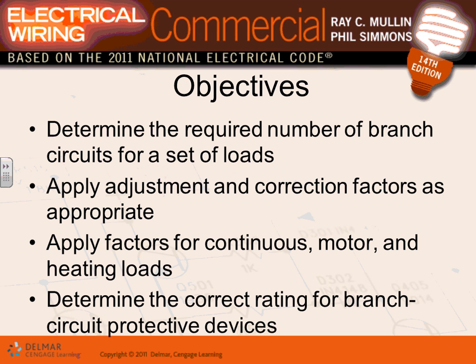When we do branch circuits, guys, I have a couple of things I want to share with you as we move on. When you grab a panel like this, you don't bring two conductors in a half-an-inch EMT conduit and pull them for the receptacles. I hope you don't do that. We group them. When it comes to the branch circuit, there's something called grouping. Those who did electrical work understand fully how we group circuits.